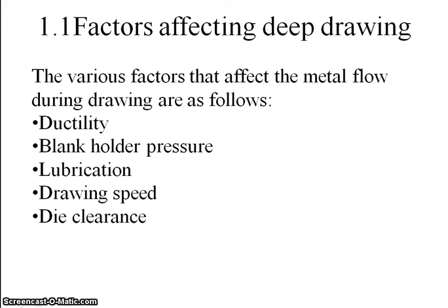Drawing speed. It is the velocity at which the punch penetrates the workpiece. When cracking or excessive thinning occurs, the drawing speed should be reduced. In general, the drawing speed should be less for harder materials and more for ductile materials.